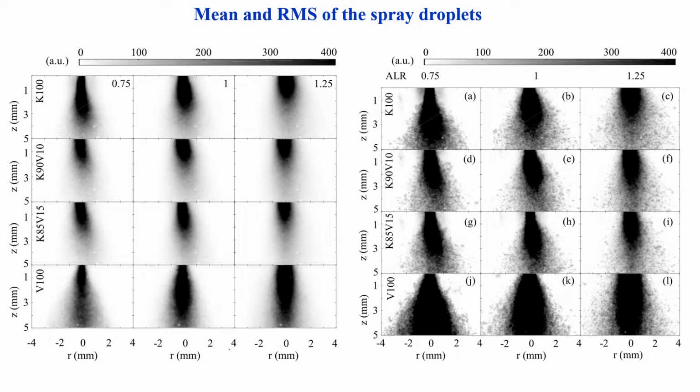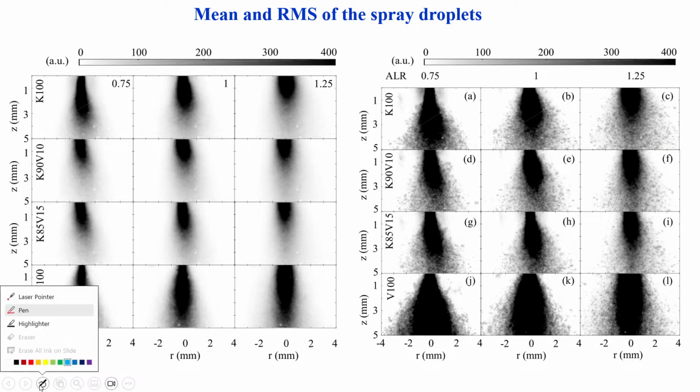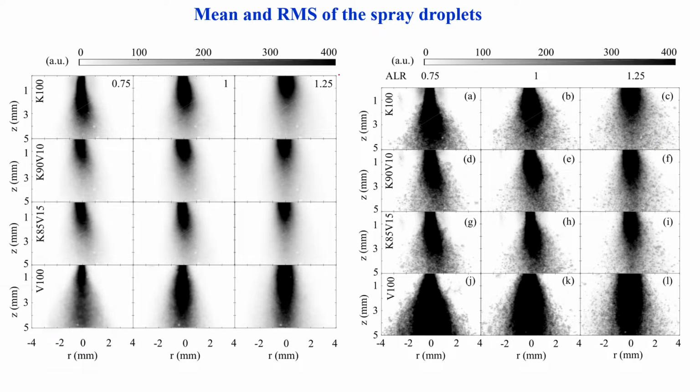Here we can see just 5 mm, I mean the exit of the injector, captured very closely. Think about 5 mm, this is a very small quantity, small in size. So we used an ultra zooming high speed Mie scattering technique to capture this to understand the near field atomization mechanism. Here we can see clearly the spray morphology is entirely different for the different categories.